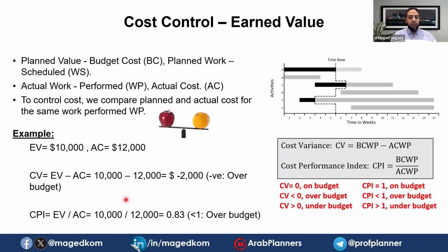So with this calculation, if we are doing it in periodic reporting, we can know in every report, on every period, what is the status of the project. Otherwise we would wait until we do the whole work at the end and then see if the actual cost is more than the budget or less, so we know whether we are making profit or not. Now if we do it on a regular basis during the construction using earned value, we can know if we are making profits or not. So what will be good about this? Why do we need to know while doing the project whether it is profitable or not?